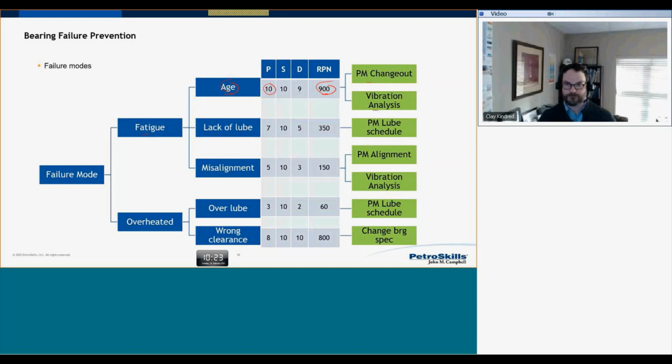You're going to say, almost certain. What's the likelihood that your computer is going to fail today? Very unlikely. The only thing we've changed is the time period. So when we talk about probability of failure, that's a probability within a specified time period. Now that also implies we can change the probability of failure by changing the maintenance interval.